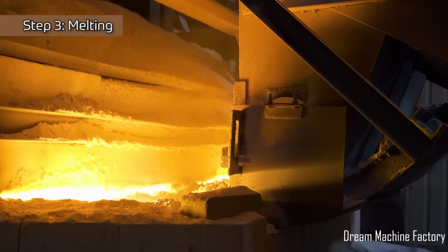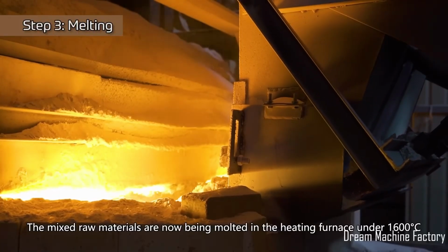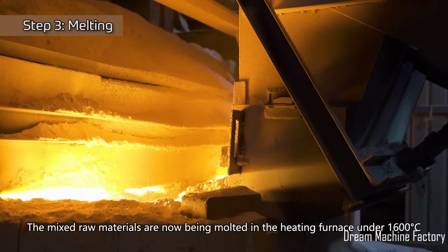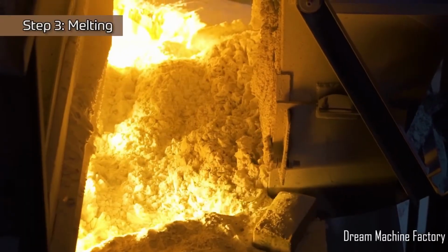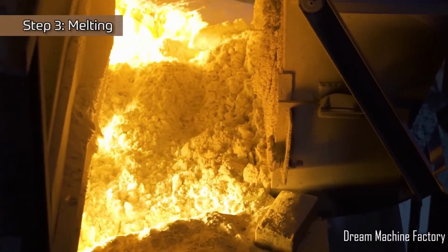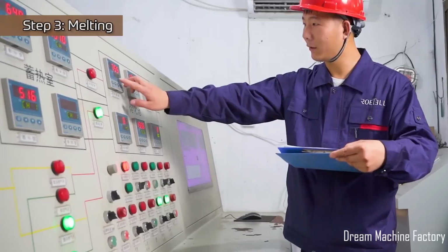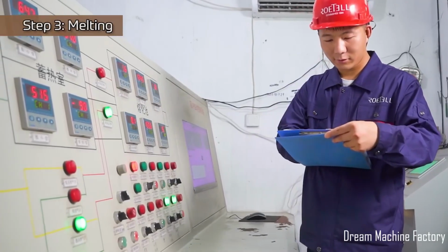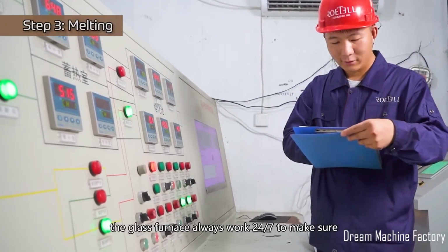In Step 3, the precisely mixed batch is fed into a high-temperature furnace, heated to around 1,600 degrees Celsius. Here, the materials melt into a homogeneous molten glass called gob. The furnace operates continuously to maintain a stable temperature, prevent defects, and optimize energy efficiency, ensuring consistent quality for subsequent forming processes.